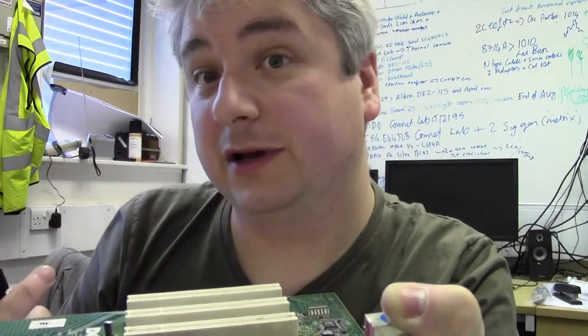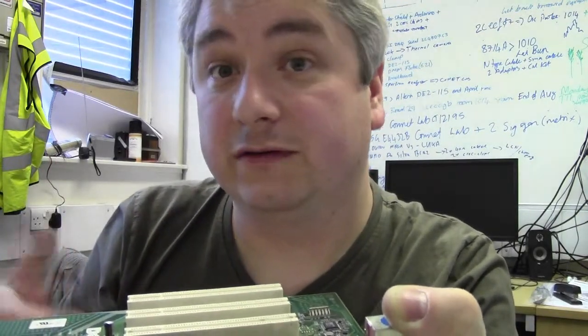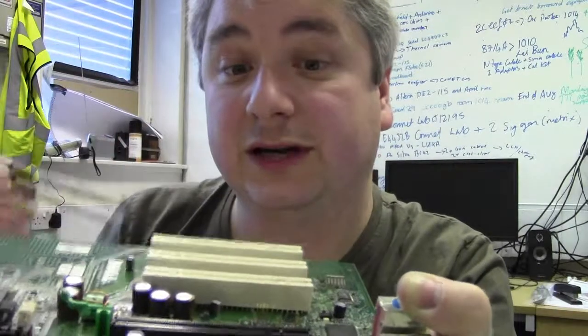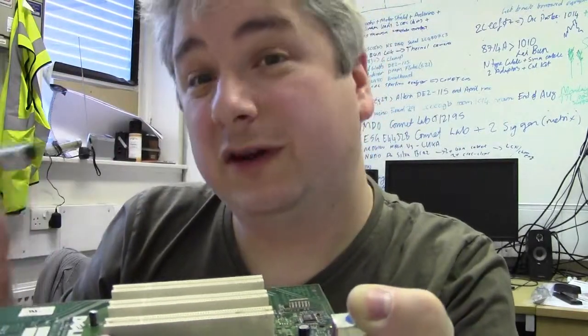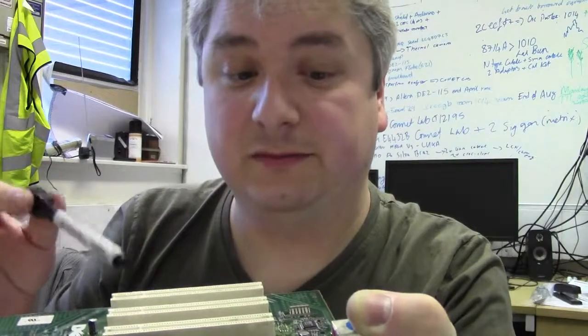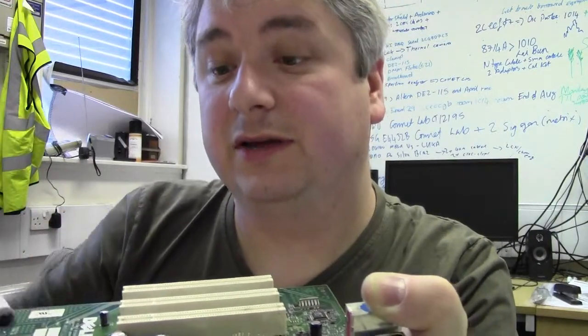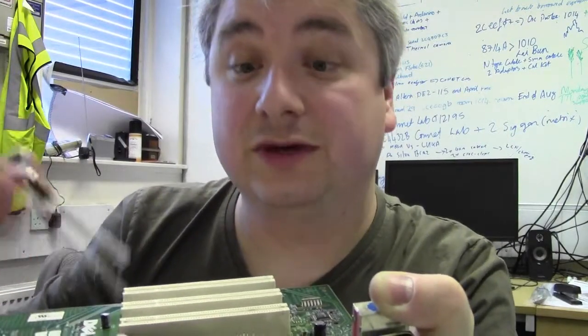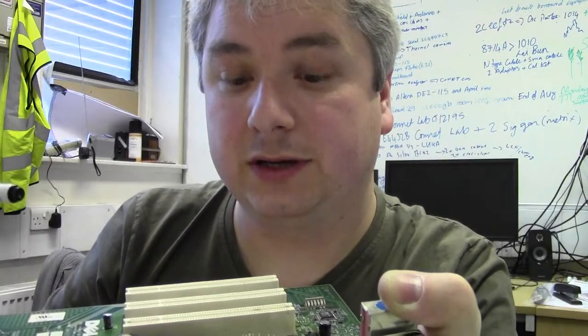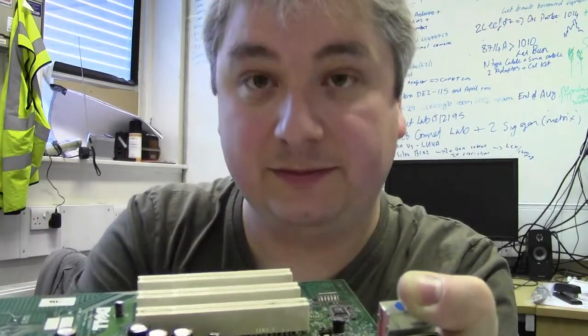You can mash it a little bit closer than what it could be. You may want to go over the voltage ratings slightly on your caps or on your resistors, provided that they fit the board. But you also have to be careful about the pitch, to make sure it actually fits the holes, and also that your lead thickness fits the holes.